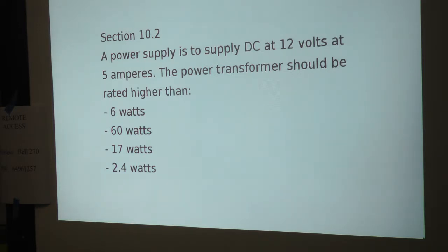The number one way I'd imagine is because a lot of them use an electrolytic capacitor. If that starts to dry out, or if it explodes, worst case scenario, then you basically have no capacitance there and you will get no filtering. Especially if the radio wasn't in use for a long time. Exactly, electrolytics can dry out over time. Isn't there a correlation with heat? The heat's a killer, correct?